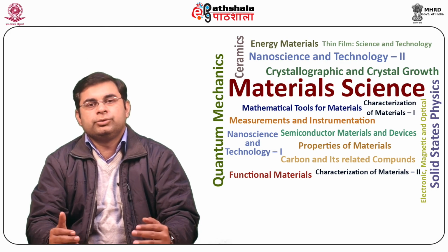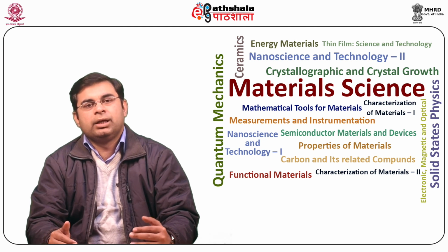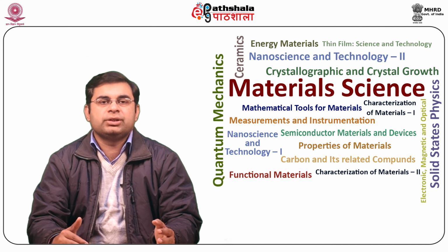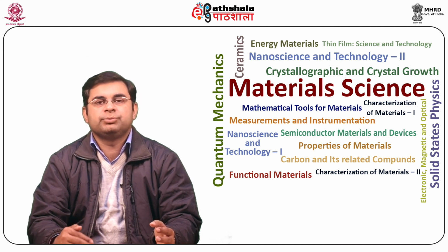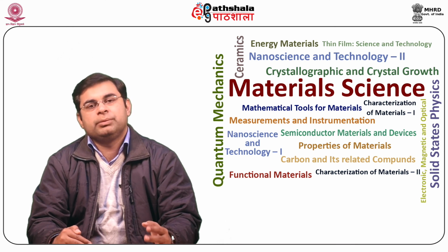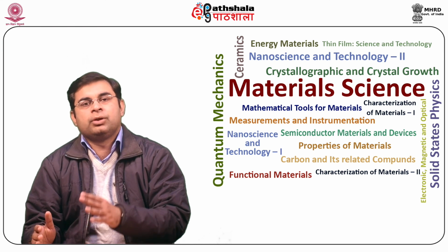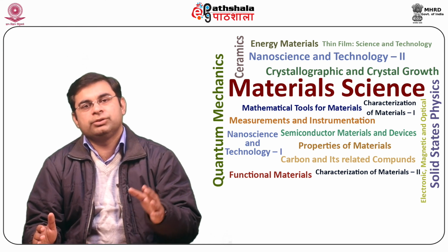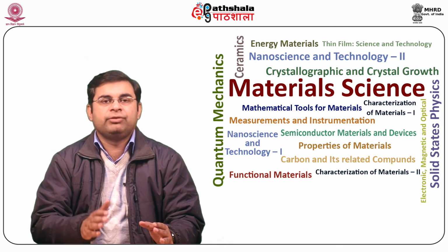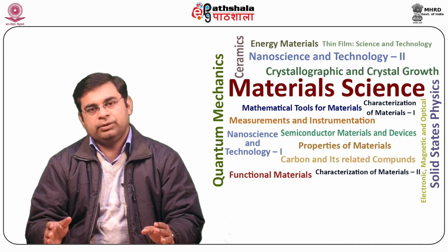In addition to this, electrolyte 2 doesn't create any rounding of the crater edge, that is, enhanced etching at crystal edges is minimum, as evident from the optical microscope image of the etched crater and stylus surface profiling after the ECV measurements, included in figure 7a and b respectively.